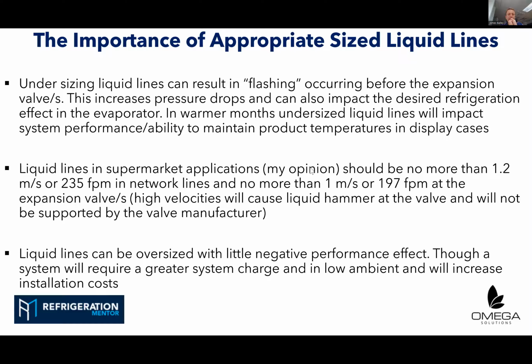Now, I'll tell you what is interesting. And as I said, Trevor, I take an agnostic approach in terms of CO2, A2Ls. But a big positive with CO2 is due to its density, due to the high pressured nature. A lot of what we've discussed, so going back to suction line sizes, you don't often get low load problems and oil problems because the pipe work's much smaller anyway to begin with.